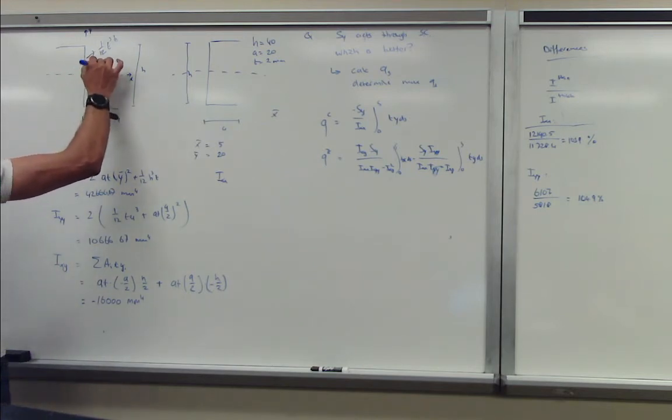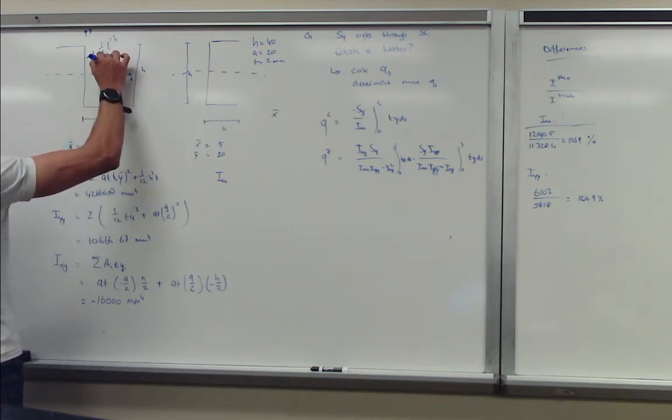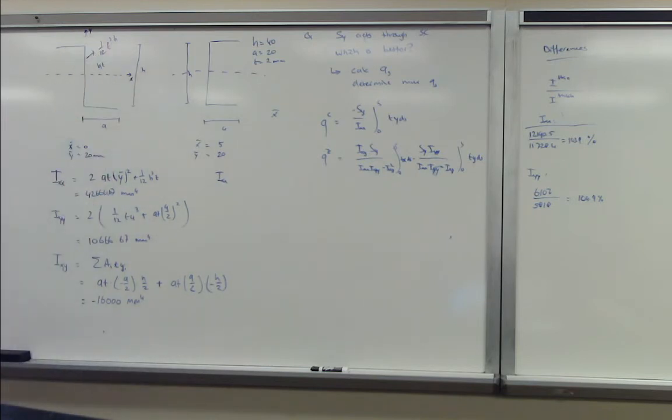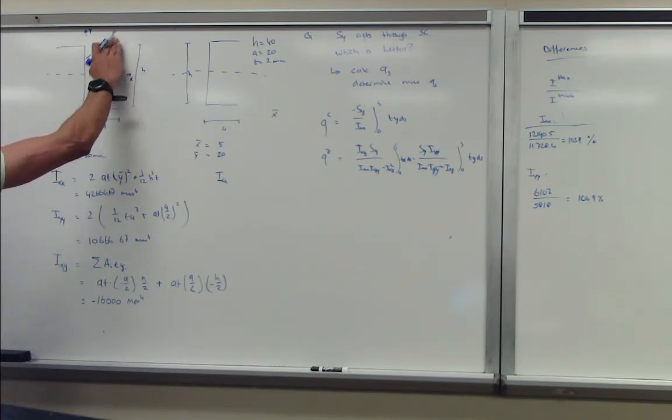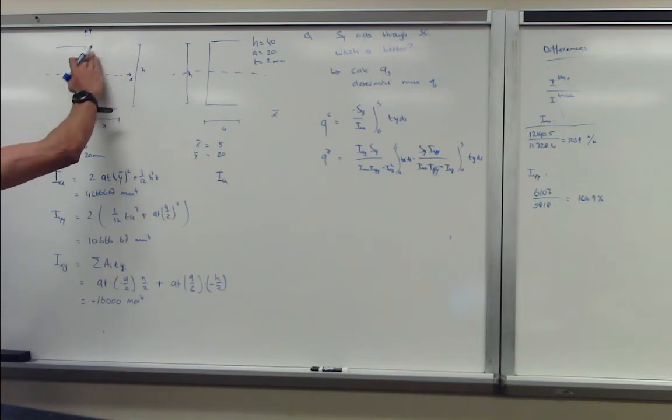And the standard term is HT multiplied by 0, because of the coordinate systems. So we could just ignore all the terms that are squared and higher, because we have thin wall. That's what we started off with: we assume it's a thin wall section, so we automatically ignore anything if D is equal or greater than T squared.